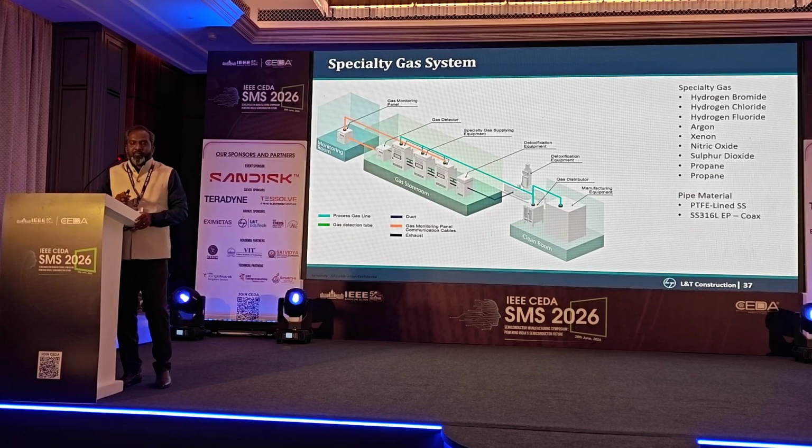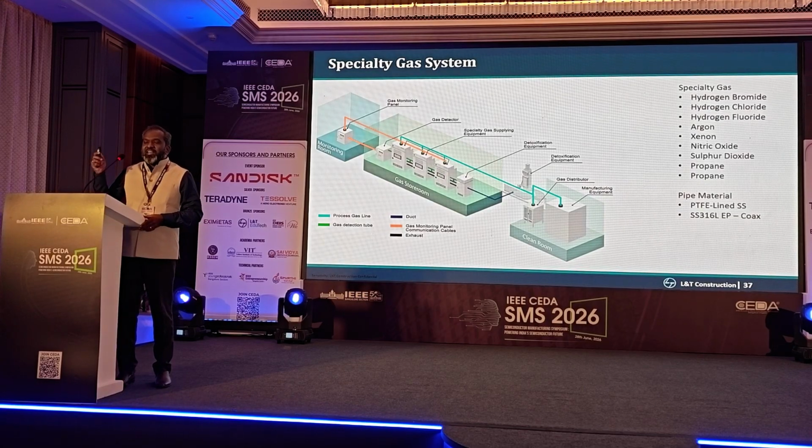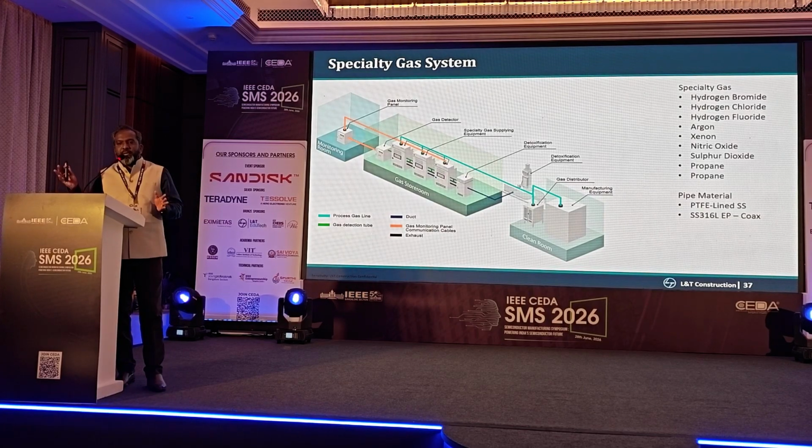So it is PTFE lined stainless steel pipes, and again certain things, stainless steel pipes, electro polished with coaxial. So what happens is this system requires a lot of monitoring. It comes in small totes, gets stored next to the fab, and the room is monitored for any leaks. Each gas type has a separate room. The CDU, the distribution cabinets, gets monitored for any leaks. So there is a continuous monitoring process of any leaks because we cannot afford to have these gases being leaked out to the environment.